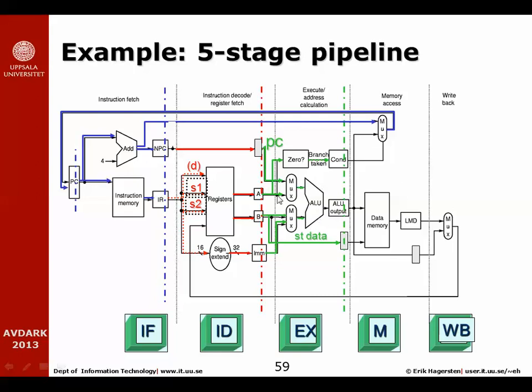If this is a branch that's executed at the very same time, we may want to know if the value from one of these registers is equal to 0. So that's what we'll take the value up here, and this 0 question mark will produce a single bit that will be stored over here in this output latch, conditional output latch.